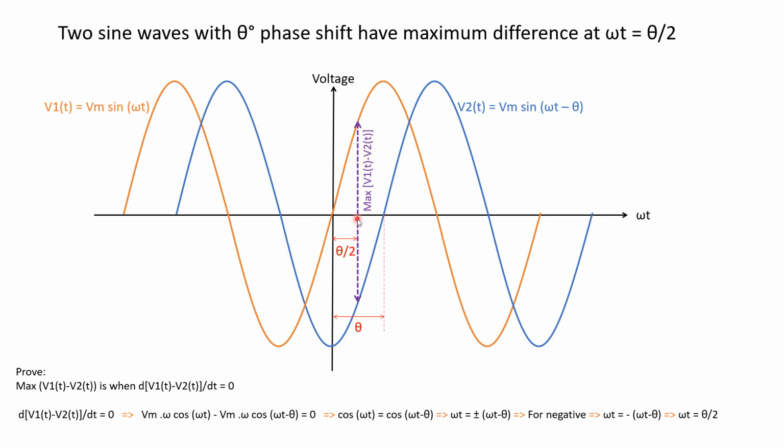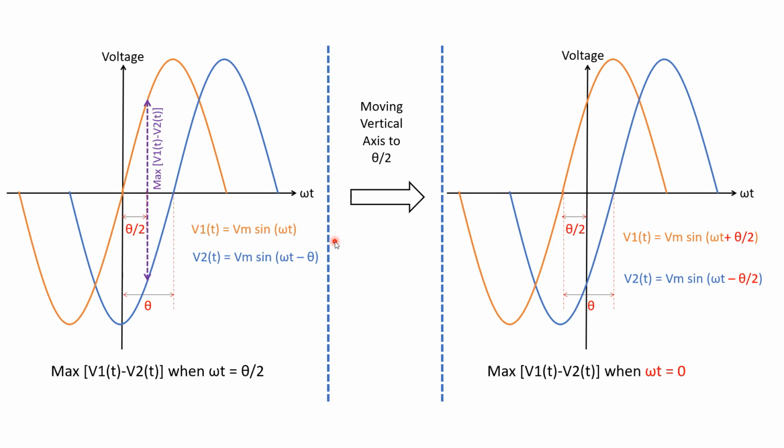So this is very important, because normally when you're using time domain software or transient software, they use many switchings at different times to calculate the worst point. But in this case, we know where the worst point is. The worst point is theta, equal to any phase shift between the two. The worst point, where we have the maximum voltage over the circuit breaker, is at this point, theta divided by 2.